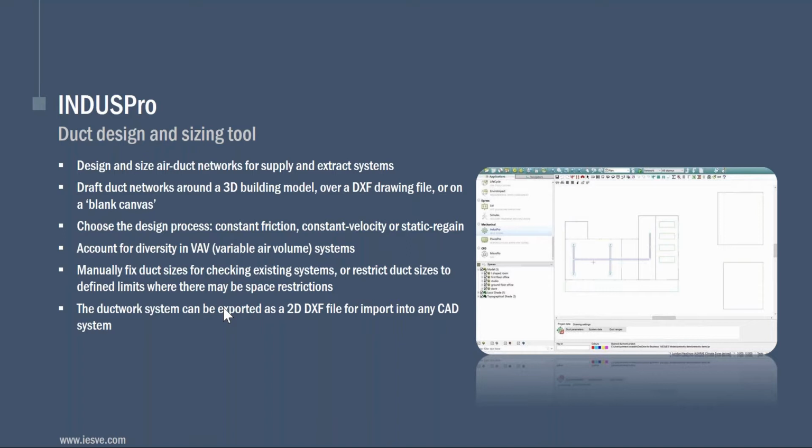Now, you can use this tool for a number of design processes. These are mentioned here, be it constant friction, constant velocity, or static regain. It also accounts for diversity in variable air volume systems. So if you're working on a specific variable air volume system, you can choose that from the options available within the platform.